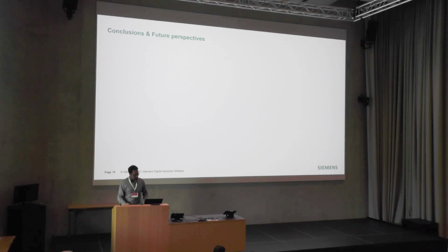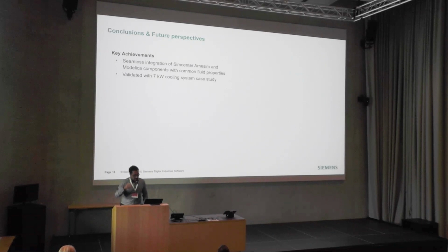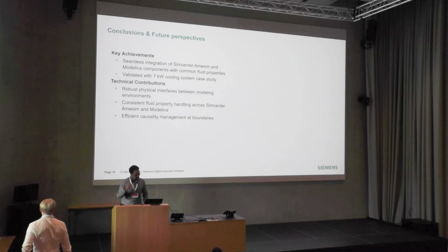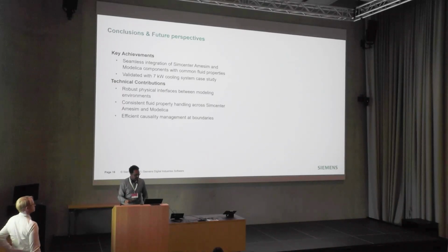Now let's move on to the conclusion of the presentation. So key achievements: seamless integration of Simcenter Amesim and Modelica components with these common fluid properties. And we validated this work through a cooling system case study. The technical contributions here: the robust physical interfaces between modeling environments, consistent fluid properties handling across Simcenter Amesim and Modelica, efficient causality management at boundaries.